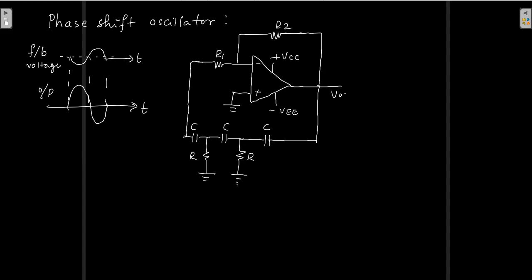You should be able to understand here how exactly it works, right? You have got a total phase shift of 180 degree, and these combinations of R and C, right? Each combination will provide approximately how much phase shift? You should be able to quickly recall these things. Approximately 60 degree, is it not?